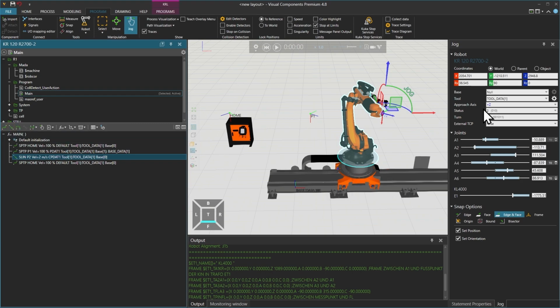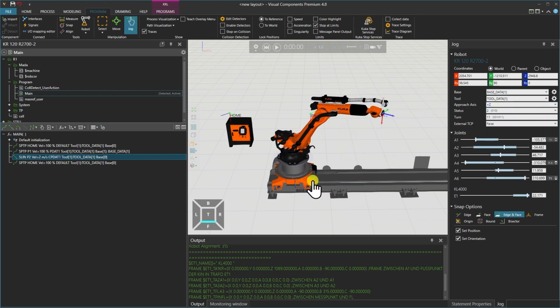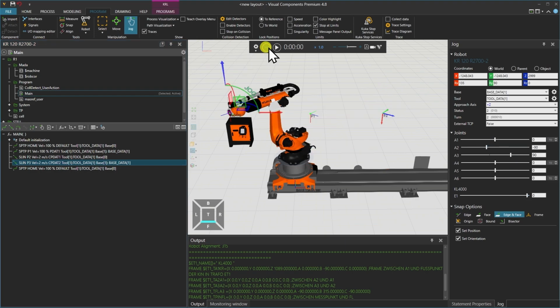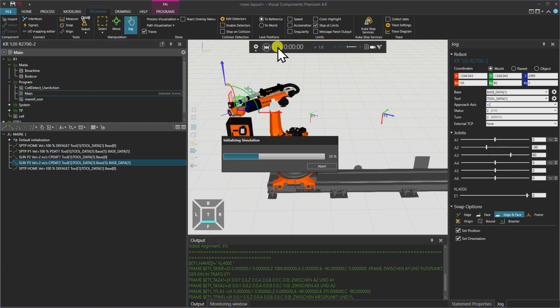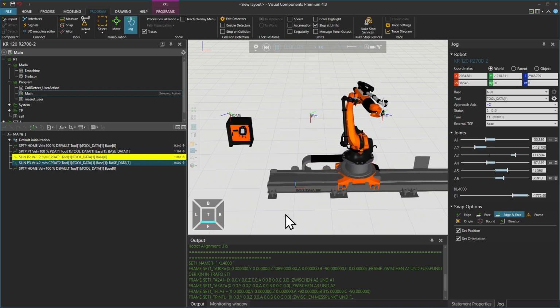And now I want to stretch the robot again, something like that. Stay in the same position, just stretch it a little bit more, and again make a linear movement like that. And if this is done, I can now reset my simulation and click on play. And the robot will do as in reality.